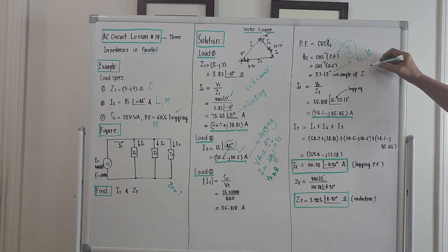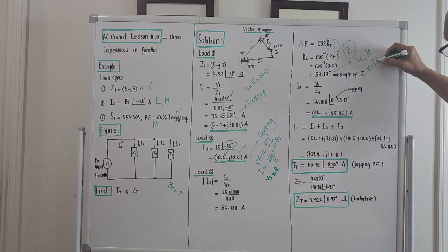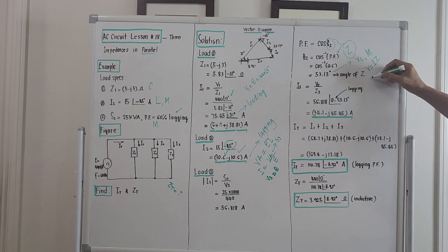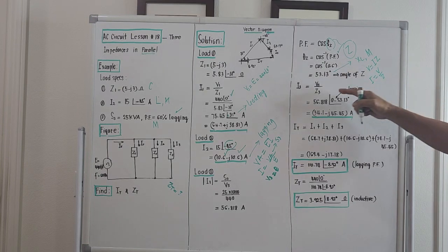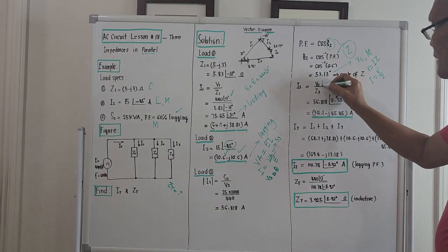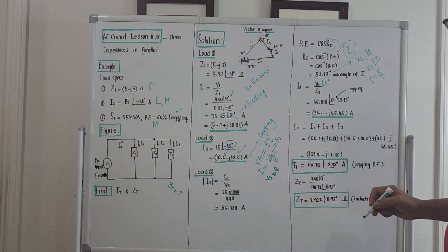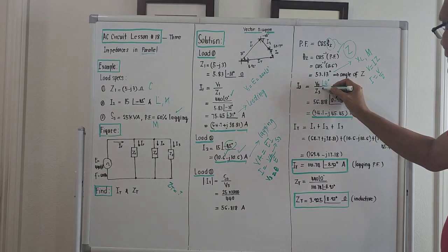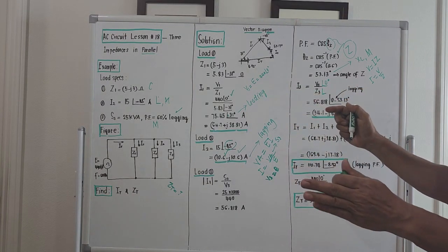And again, if we try to bring out the formula for volt ampere, the product of voltage and current, the product of current times impedance is actually voltage. So current will be voltage over impedance. So I3 now will be V3 over Z3. Actually, V3, this is with angle 0 degree, right? And the impedance, we have computed already the angle of the impedance.